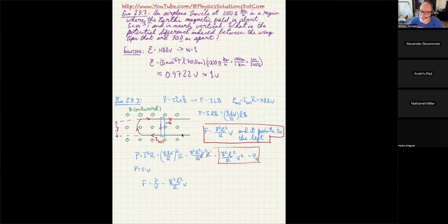And remember, P equals I squared R would mean, oh, wow, we're reducing the lost power by a factor of 10,000 squared, which would be 100 million. So that's part of why we do what we do in stepping things up and down like that. But to understand that, you need to know Faraday's law and then the transformer equation, which is easy peasy.